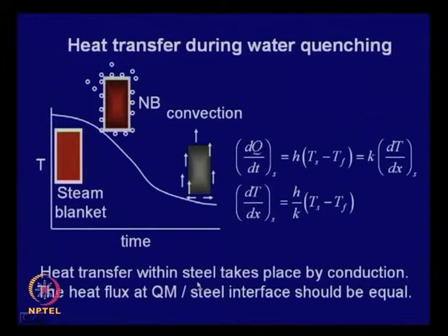Now, heat transfer within the steel, of course, within the job, can be solved by the normal conductive heat transfer technique, which is quite well established, and it can easily be done by Fourier series kind of solutions. But let us look at a much simpler approach which will be quite useful in designing a heat treatment process.